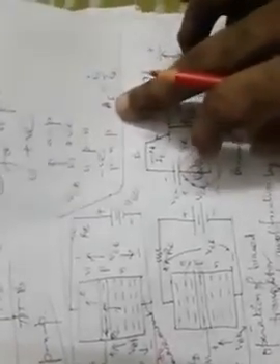The quantity AI is slightly less than unity, because we have seen what AI is. AI is nothing but IC by IE, and we have already seen that the collector current and emitter current are almost equal, because IB is very small, a recombination loss current part. So if IC and IE are almost equal, the current gain for a transistor amplifier is almost unity, which is the ratio between collector current and emitter current.